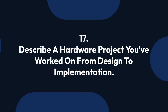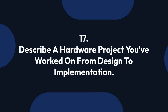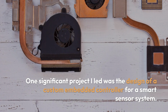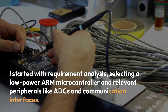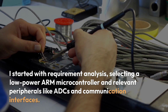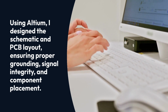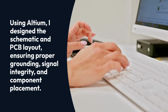17. Describe a hardware project you've worked on from design to implementation. One significant project I led was the design of a custom embedded controller for a smart sensor system. I started with requirement analysis, selecting a low-power ARM microcontroller and relevant peripherals like ADCs and communication interfaces. Using Altium, I designed the schematic and PCB layout, ensuring proper grounding, signal integrity, and component placement.